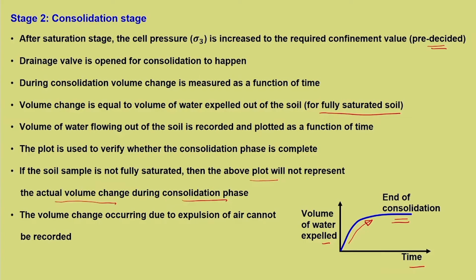So, that is the reason it is important that we need to have complete saturation, and this particular curve is very important to decide upon the shearing stage, like when it comes next. Especially that will become important for drained shearing. So, this particular information becomes important.